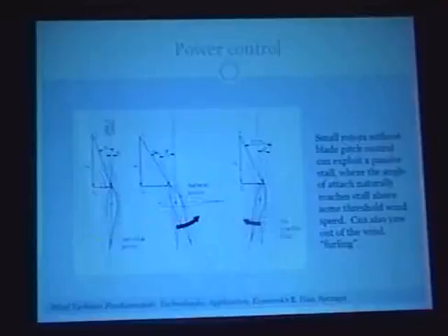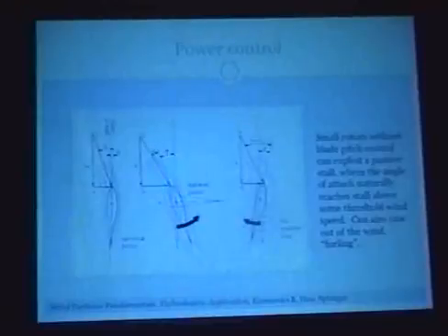Yeah, so you have mechanical ratings and electrical ratings on your generator. And for a given site, you put a generator in with some finite rating, and you don't want to exceed that, like say, if you get gusts or even moderate speed winds, because the power goes as the speed cubed. So you really start to get significant amounts of power. So in normal operation, the wind is blowing in this way, and one thing you can do if you don't want as much power, you can change the attack angle so it's effectively zero, and that really drives the lift down, and that manages the speed of your turbine.